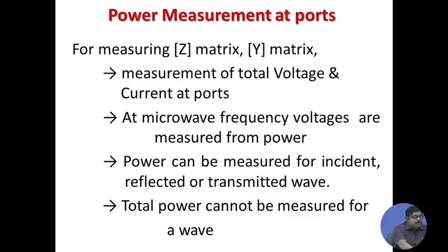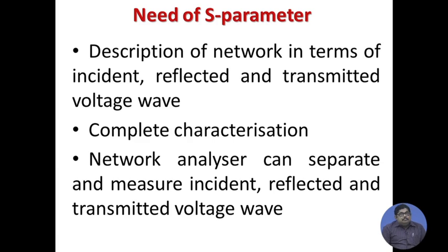We will have to say what is the incident voltage, what is the reflected voltage, what is the transmitted voltage, etc. That is why when we try to characterize a microwave network, we cannot characterize it directly in terms of Z, Y, H, A, B, C, D. We still can do it indirectly, but if we want to measure these parameters, then we need to measure the